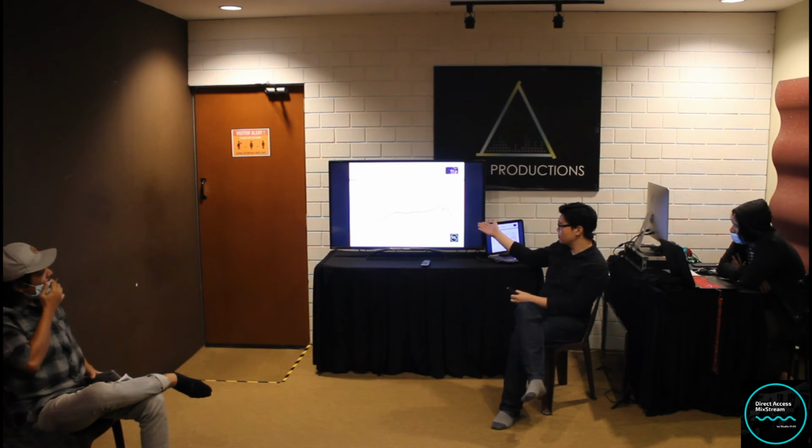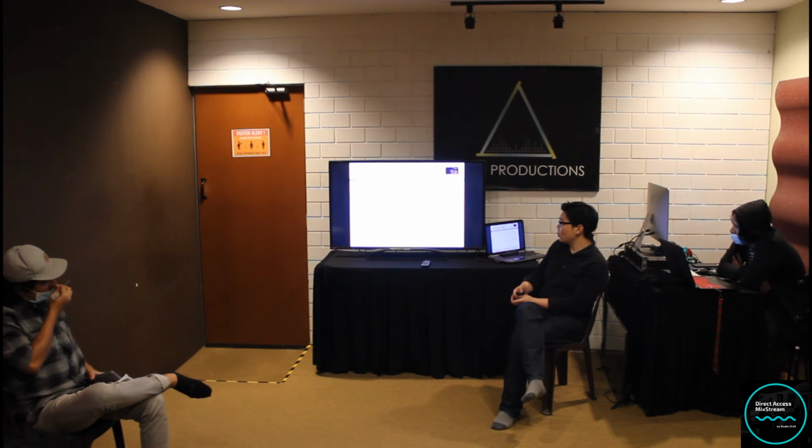So looking at the frequency response can tell you the characteristics of this microphone already. You will have that presence peak, and it has a roll-off under 200. You pick the applications best suited to this microphone's frequency response. All right, now let's go into polar pattern.